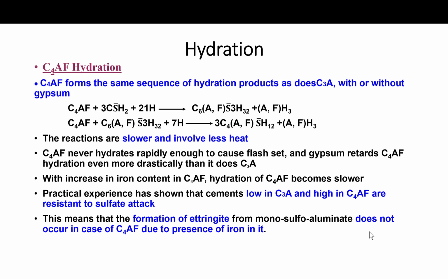The tetracalcium aluminoferrite forms the same sequence of hydration products as does C3A, with or without gypsum. As you can see in the first equation here, with gypsum, the C4AF and water give us a calcium aluminoferrite sulfate hydrate phase, or aluminum ferrite hydrate phases.